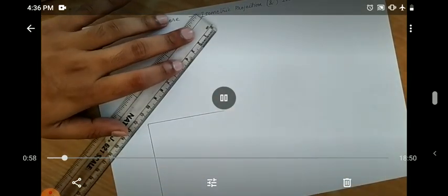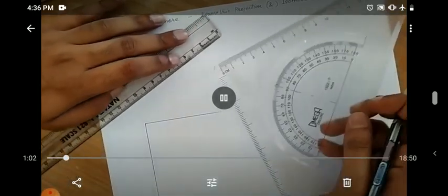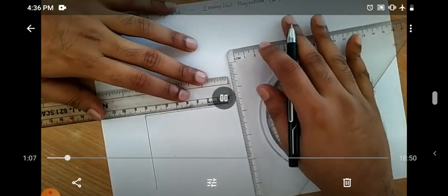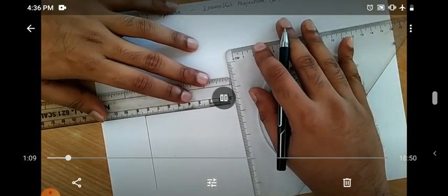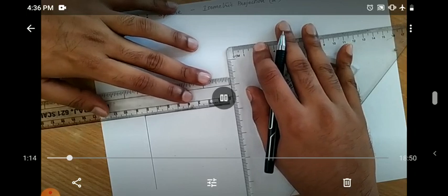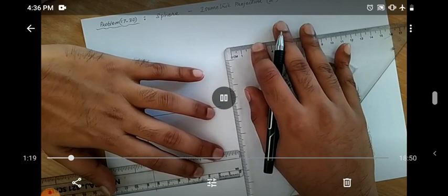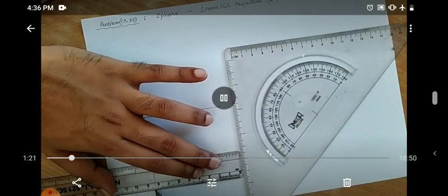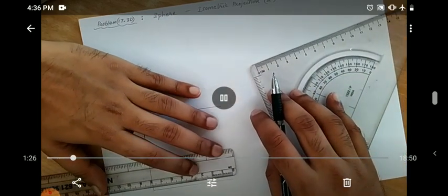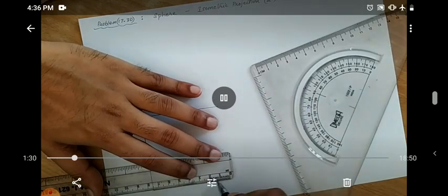See, in general, the questions will be of two categories. You will be asked to draw the isometric view or else isometric projection. In isometric view, what I have said already, that means no dimensions has to be changed. Only you have to draw the 30-degree isometric axis and take all the true dimensions as such as it is given in the question. But while drawing the isometric projection, you have to multiply each true dimension using 0.80 and take the new dimensions while drawing the isometric projection.